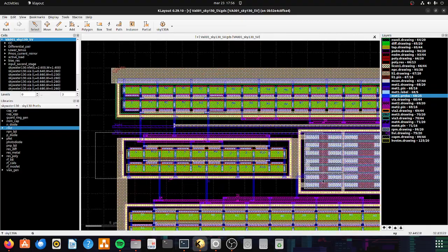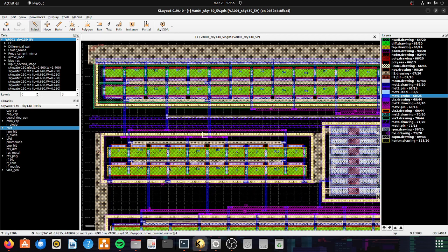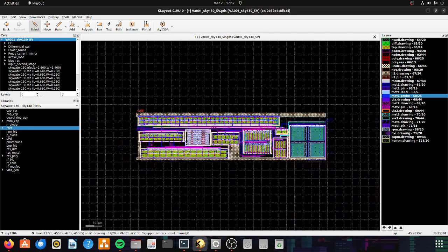This is the voltage sink of the transconductance cell current mirror. Basically the constant transconductance cell is just a current mirror. This has the same layout pattern, but because they don't share the same terminals, we have to put dummies in as their connections. This will actually improve the matching and improve proximity effects of the transistors, since it will force them all to have very equal characteristics during fabrication.